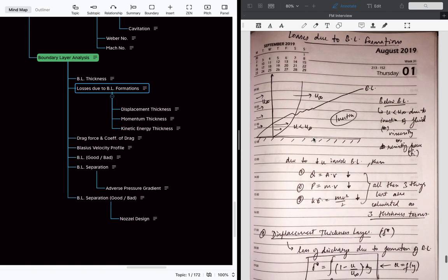So below the boundary layer, the velocity is reduced to less than the free stream velocity due to the inertia of the fluid, which happens because of the cohesive force inside the fluid, also described as the viscosity, and also the resisting force or friction force on the plate. So this creates a total overall inertia force which resists the body from flowing. Due to this reduction in the velocity inside the boundary layer, three things happen.